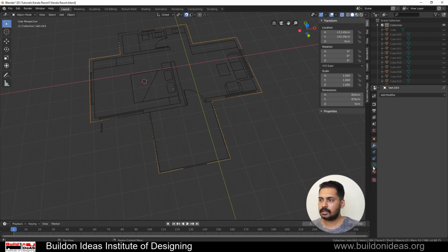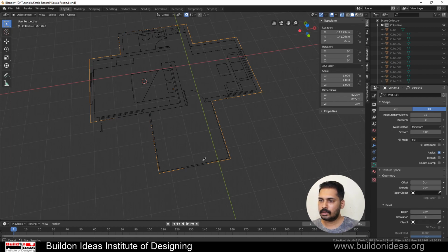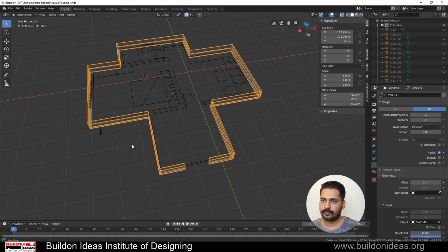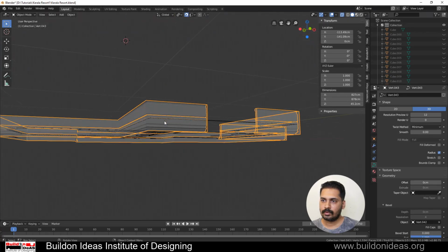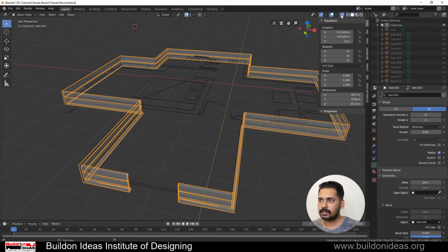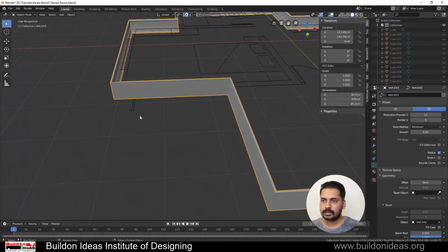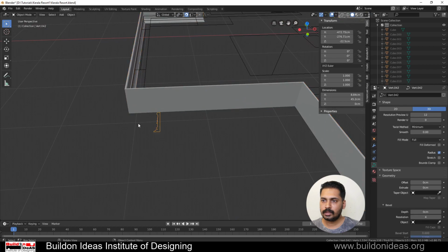So I'll just select this and then come to the curves, and then in the geometry I'm just going into the bevel and then picking this profile. You have the profile but in the opposite direction. You can see that if I click on it, this is the profile but it is inside. That is because we need this profile to be in this direction.